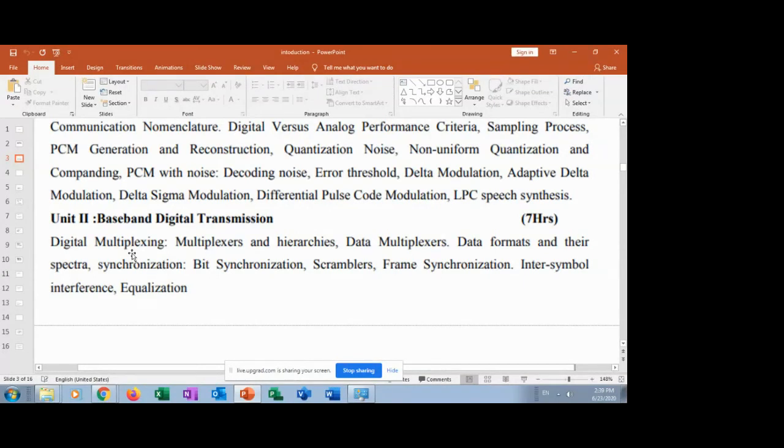So remember, in analog communication, when we have to transmit different analog information signals over the common channel, that type of multiplexing is called frequency division multiplexing. And when we have to transmit different binary information over the common channel, we have to use time division multiplexing, TDM, FDM and TDM. There are different types, and some numericals also based on the particular topic. That we will study later. Just remember the topics and what content you have to study. After that there are data formats.